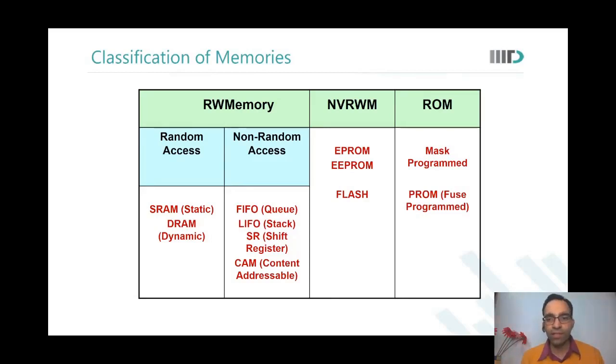Faisal, you have your hand raised. I just want to clarify a statement about shift register in FIFO. Like in shift register, due to latency, we are using shift registers. So you could also use a FIFO there. That's why I was confused, sir. Yeah, you could also use a FIFO there. Shift registers are more area efficient than FIFOs if you just need a few words.